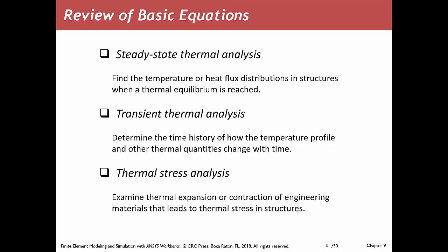Steady state, the basic definition, is independent of time. Transient is a function of time. You want to see the history of how the temperature profile develops or changes with time. And then thermal stresses: if you have a constrained body that is subjected to a heat source, metals and other materials basically stretch or shrink due to variation in temperature. And if there is no way for it to stretch or shrink due to constraints, it is going to develop internal stresses, or thermal stresses.